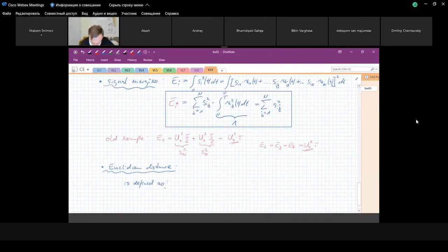the distance d between, let's say, a signal vector si and a signal vector sk. This is the Euclidean distance. Of course, i needs to be different from k because we compare two different signal vectors. The Euclidean distance is just the length of the difference vector, so it's si minus sk or sk minus si.